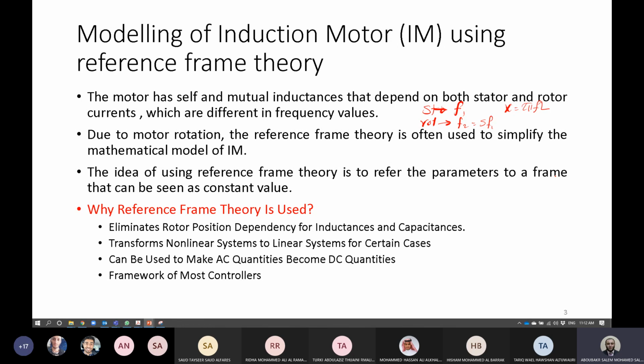Okay, it cannot be used in a speed control or vector control of machines. However, the concept of control is right. You can use the concept of control we have discussed previously in induction motor. We can use voltage over frequency control, we can add resistance, we can control frequency. All of these are possible.